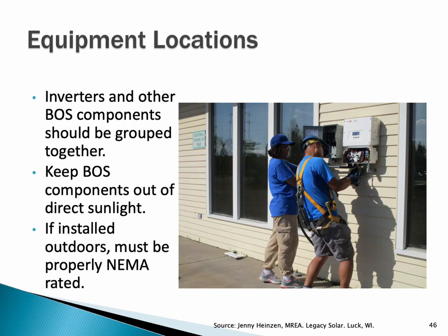And if I put it outside, even though our equipment is rated for being outside, like the inverters and disconnects and all that stuff, then it has greater swings of temperature, as low as minus 25 degrees, to all the way up to 100 degrees Fahrenheit. And if it's in the sunlight, it's going to be even hotter on the south side of the building.